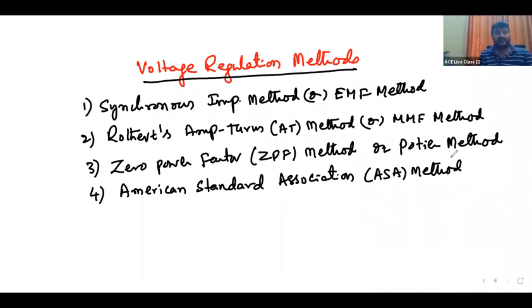But first of all, you want to measure voltage regulation. Direct method you can use. Directly you can measure: apply the load, measure the full load voltage, say 400 volts. Remove the load. Same voltmeter measures the no load voltage. So you know no load voltage, full load voltage. Then regulation is equal to (E minus V) by V. Then why to do all these things?